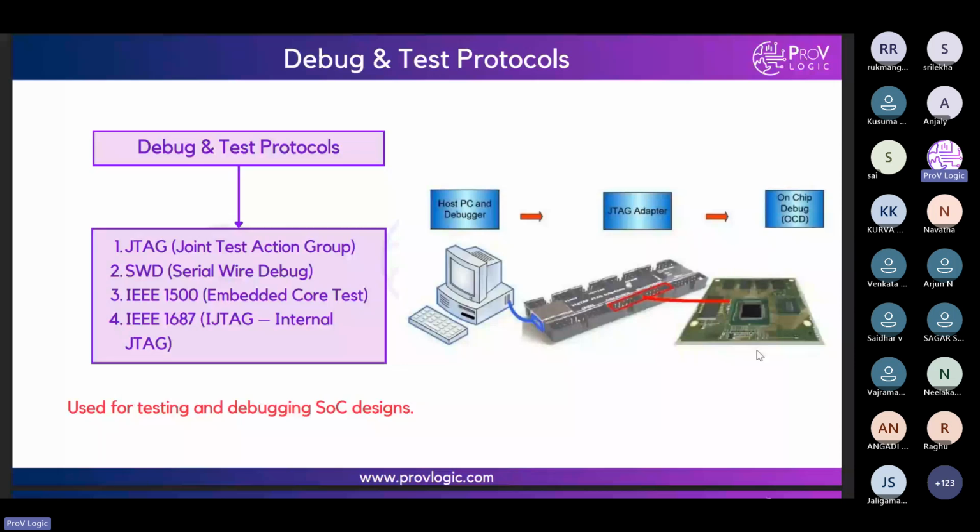Post silicon means after the chip is ready, after manufacturing is done, after tape out, we also find a lot of debugging issues. How we do the debugging here is that this SOC is connected with the debug unit. The debug unit is special, extra hardware.